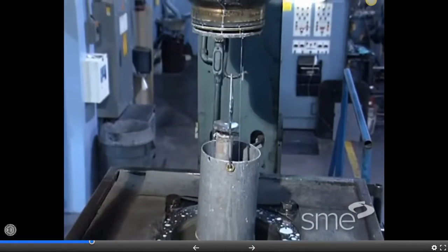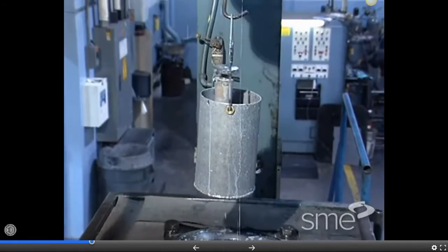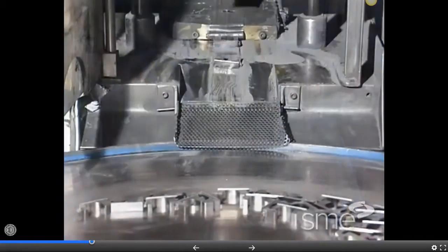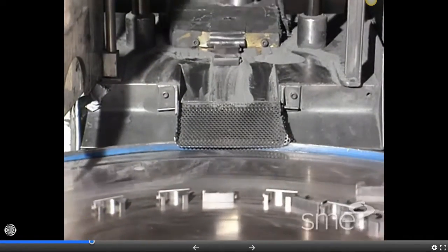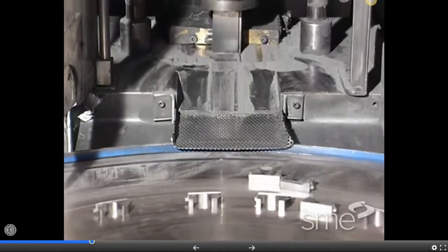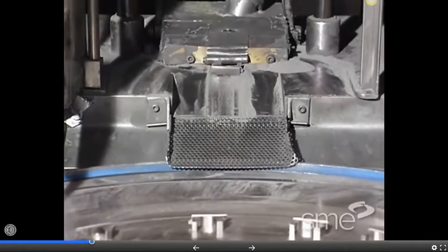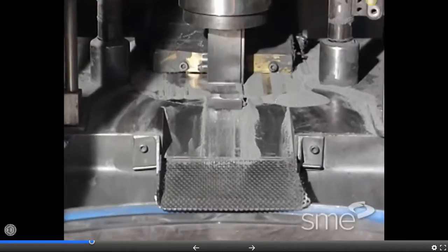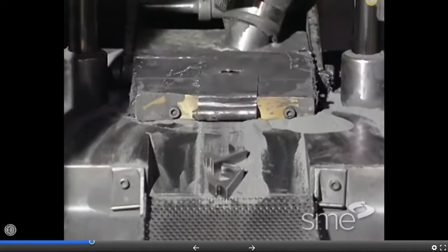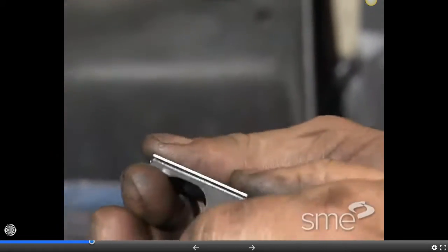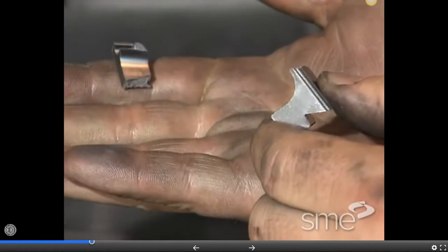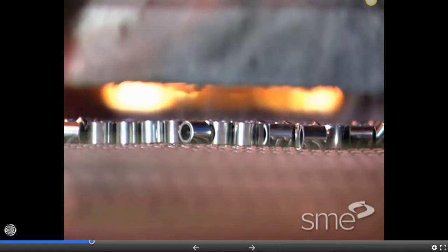The powder is then consolidated in molds or dies, shaping and densifying it into a compact of the desired part. At this point, the part, or compact, is in a green state, where the powder particles are just lightly joined together. In this state, the parts have a so-called green strength, which is usually only sufficient for handling purposes. The parts are then transferred to a sintering furnace.